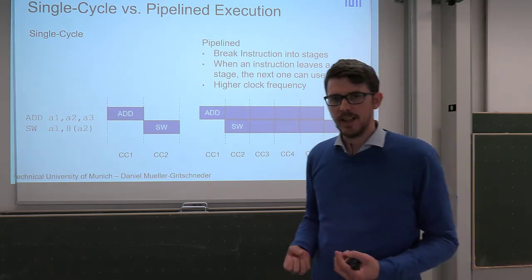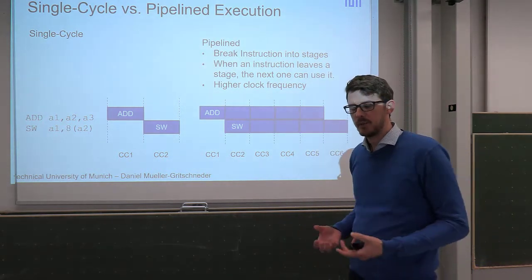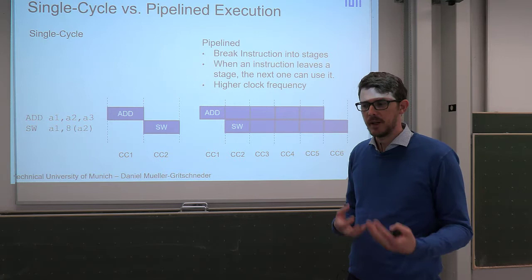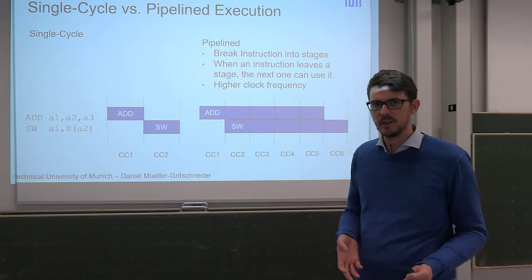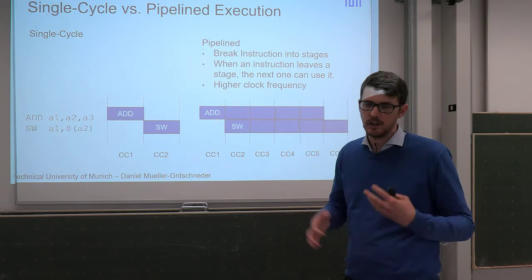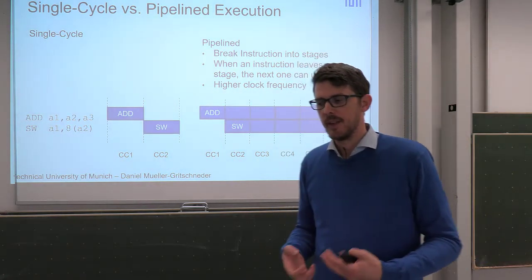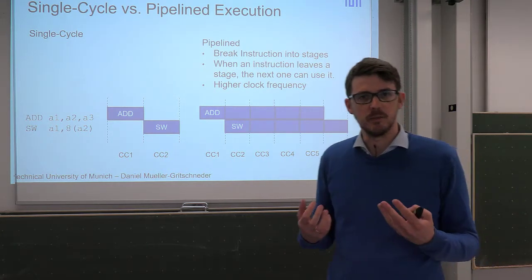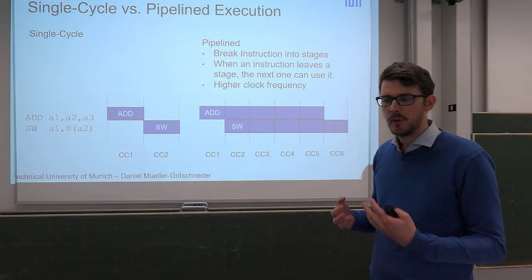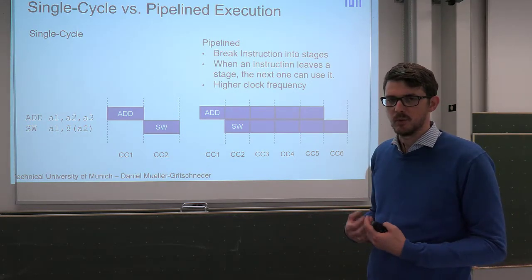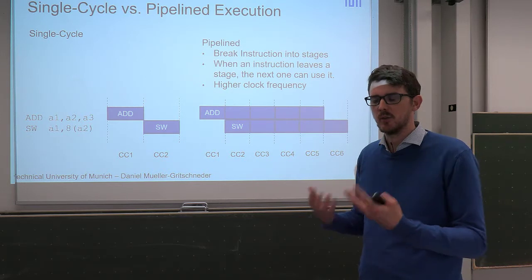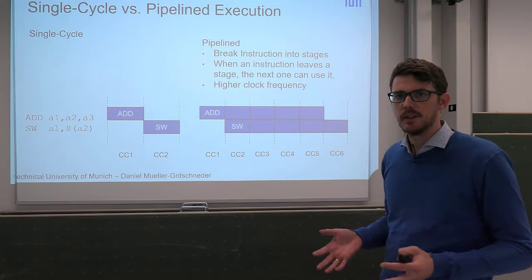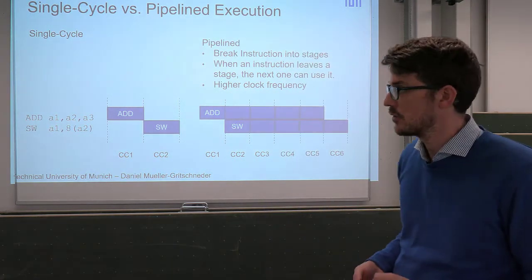And normally the more high-performant a processor becomes, the more stages you put there, right? The very small, deeply embedded low-power processors might only have, for example, 3 stages. Then these 5 stages are typical for embedded processors you might find. And if you move on to more performant processors, they might have 8 stages, even 12 stages. And then they might have not only a single pipeline, but several pipelines to do different things. So the instructions also start to be executed in parallel. Okay, but we will here look into this very typical academic 5-stage pipeline.